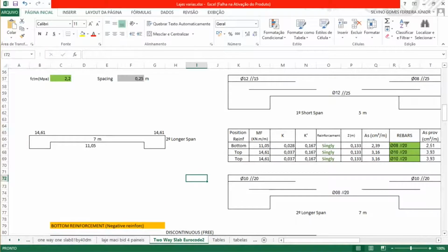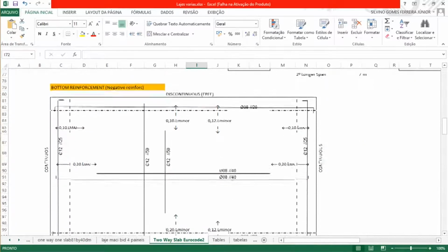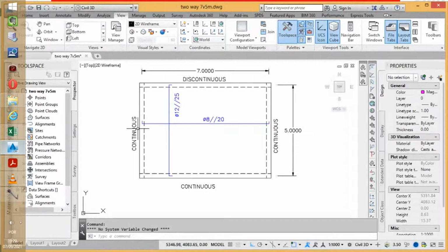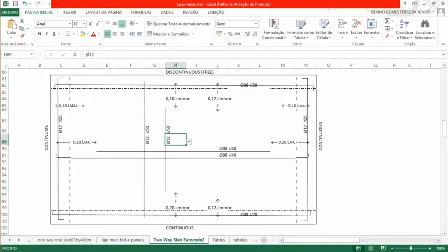If we wish, we can get more detail. This is what some software does. This diameter was spaced by 25 in this direction, 25. So if we put the diameter spaced, we double the spacing to 50, we can put one bar that is this one, and after that we put another bar that goes from corner to corner spaced by 10, and we go on that one.